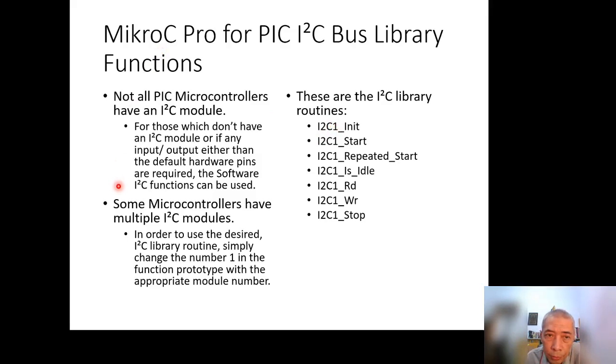But as you know, not all PIC microcontrollers have an I2C hardware module. For those which don't have an I2C hardware module, you can use the software I2C module. But I don't suggest this because in many cases it doesn't work anymore.